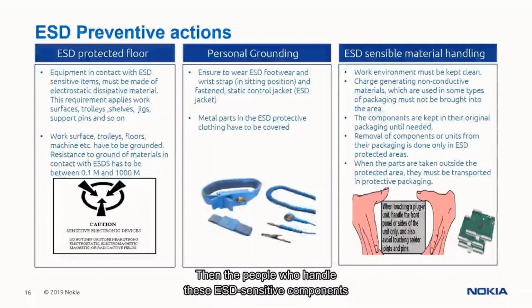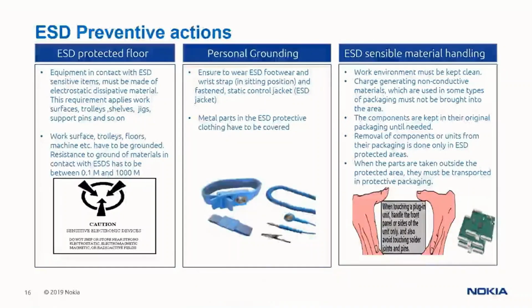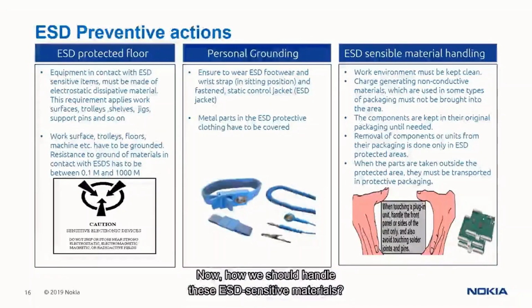Then the people who handle these ESD sensitive components must wear an anti-static wrist strap and ESD footwear. And if they are wearing ESD protective clothing, then there should not be any metal parts exposed to the ESD-sensitive components. Now, how should we handle these ESD-sensitive materials?